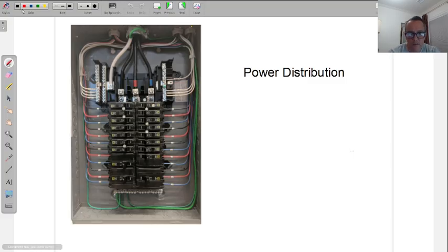When it comes to the transformers and all the voltages that I was talking about with delta, the delta high leg, corner grounded. First of all, high leg delta and corner grounded delta will probably be very rare. High leg you may run into, corner grounded unlikely. These days they're just phasing out of the world of electrical. So more likely you guys will be running into Y fed systems. All right, Y fed systems.